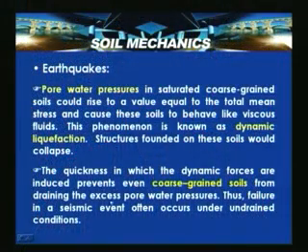In such situations, we can say that under these kind of undrained conditions, where there is no possibility or time duration for drainage, failure can occur in the undrained condition. One major phenomenon which actually governs earthquake induced failure for a slope is dynamic liquefaction, and the quickness with which the dynamic forces are induced prevents even coarse grained soils from draining the excess pore water pressure. Thus, failure in a seismic event can occur even under undrained conditions.